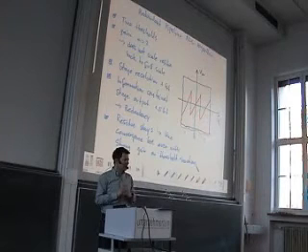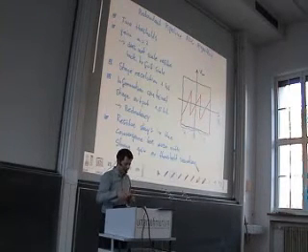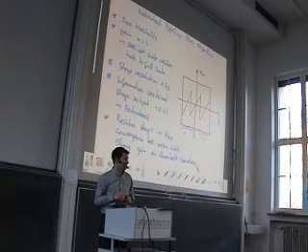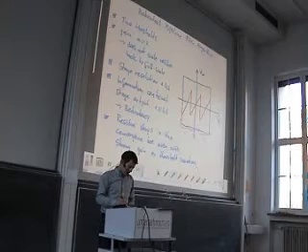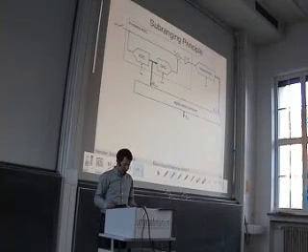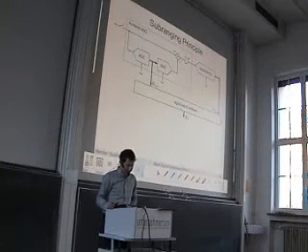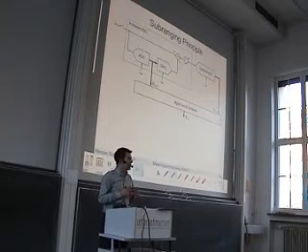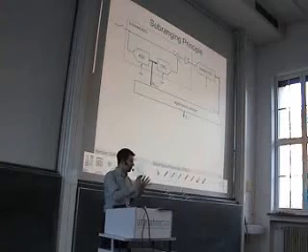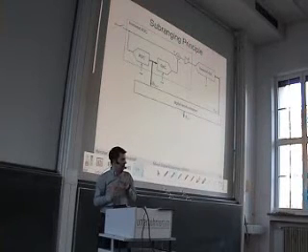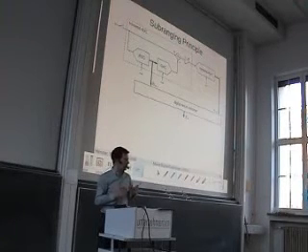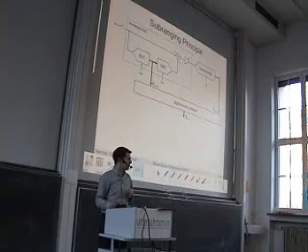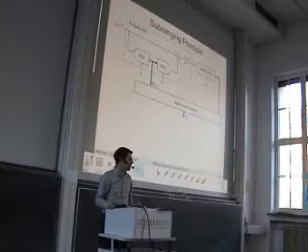So how can we compute the final result from these 1.5 bits falling out of each stage? I will explain this with this subranging ADC, and subranging here means that we only have a pipeline of 2 stages. So we have 1 stage and a second stage. And therefore, with this structure, we can understand everything, and then we extend this to n stages, which is at the end the same.